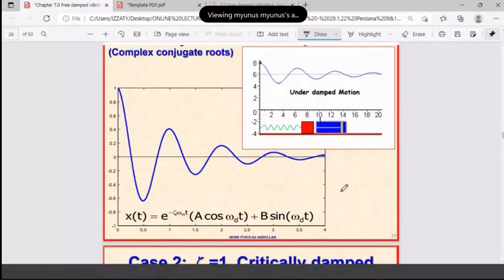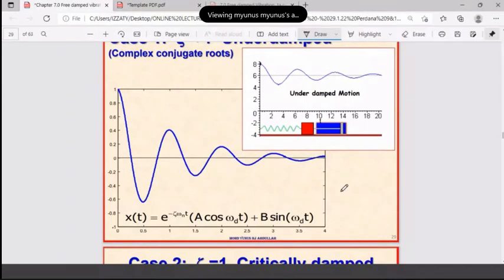Doctor, normally in the example of the car we use overdamped or critically damped. We use underdamped. Everything that we use is basically underdamped. But when we wish, for example, it can turn out to be overdamped or critically damped. For example, your absorber now of the car is worn off and cannot be used. Or you can see from the absorber itself, you have oil, a spill of oil, coming out from the chamber of the absorber.